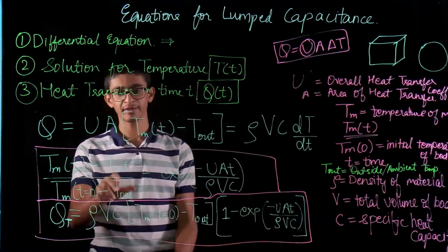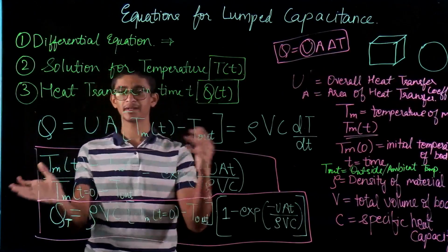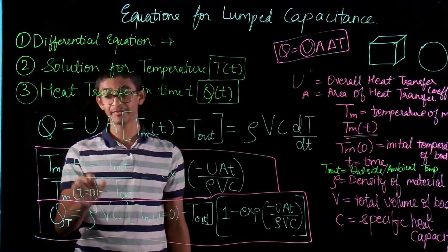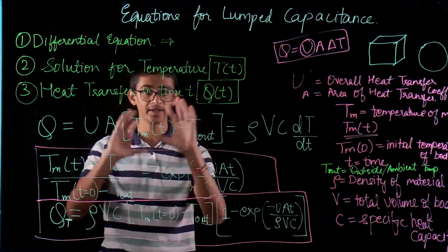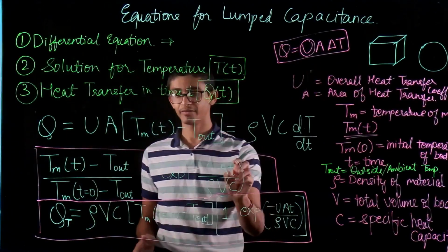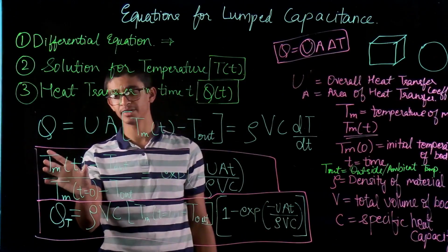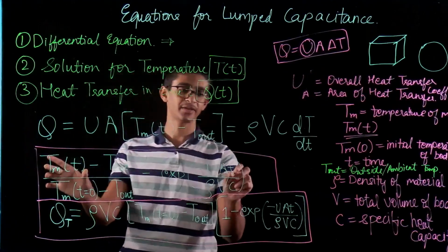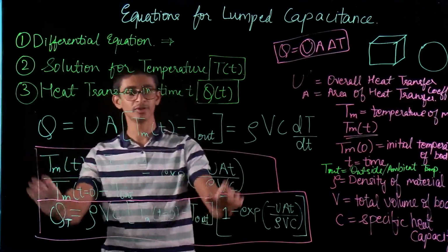So if I have a given outside temperature and initial temperature of the mass, let's say the outside temperature is 30 degrees Celsius, my initial temperature is 75 degrees Celsius, and the UA value of my building envelope is available, and rho V Cp of my building is known, we can calculate the temperature of my building, the concrete, the wall, or the air inside my building after, let's say, 6 hours, 10 hours, 20 hours, and this formula will be helpful.